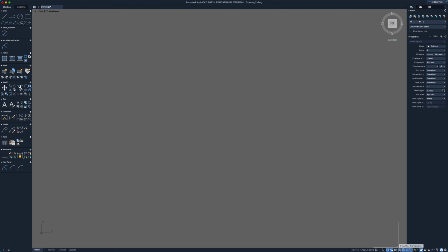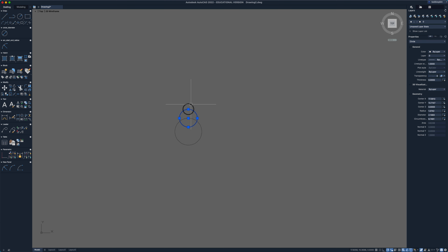Okay, show hide transparency. Usually I just keep that one off, and we can look further into what that does as it's needed. The one to the right of that, which is your group selection, is very useful, and a lot of people forget that they can use this function. So as I create an object, say a circle with another circle and another circle, we have three different objects here, 1, 2, and 3. But if I want to, I can group these, so put them all together. So I go G, enter, that allows me to select it, and now it's a group.